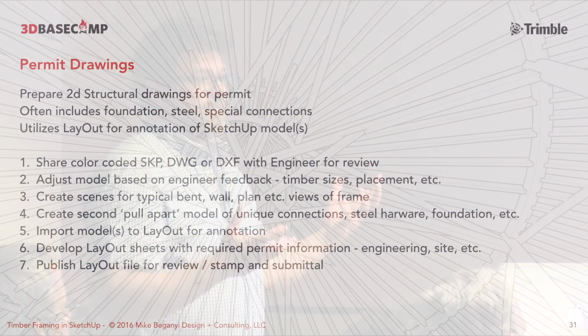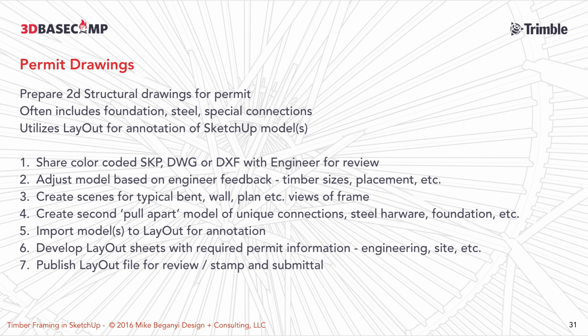Oftentimes I do the foundation, the steel connections. Sometimes I do shear walls if I need to. I'll detail all that stuff as well. So it's kind of a lot of stuff. This is definitely where I'm using LayOut more than just for creating a pretty picture with a logo on it. I'm actually using LayOut to control visibility of the sections and the scenes that I've set up, and I'm putting a ton of information over the model.